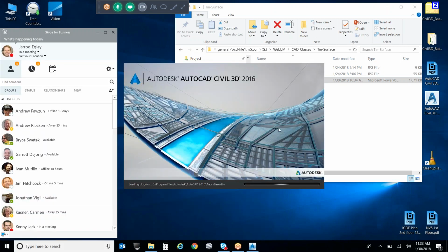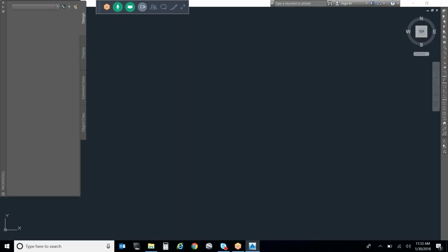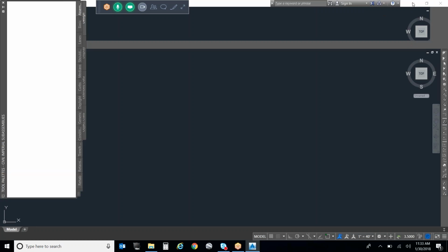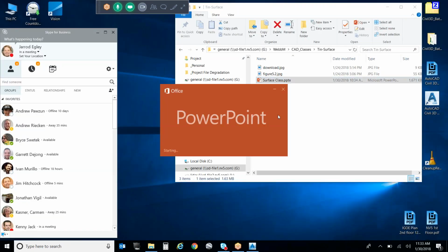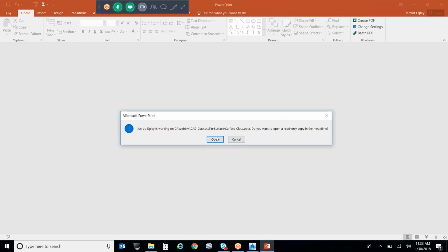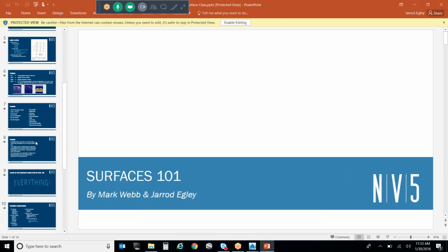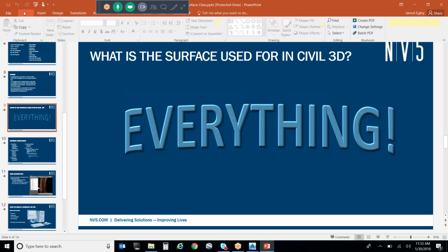If the surface is plus or minus 6 inches, and you're doing something over 25 acres, I've seen that go down to 0.01 of a cubic yard. That accuracy isn't there. You're good if it's about 100 yards. So again, keep in mind the accuracy of the data that you're using.